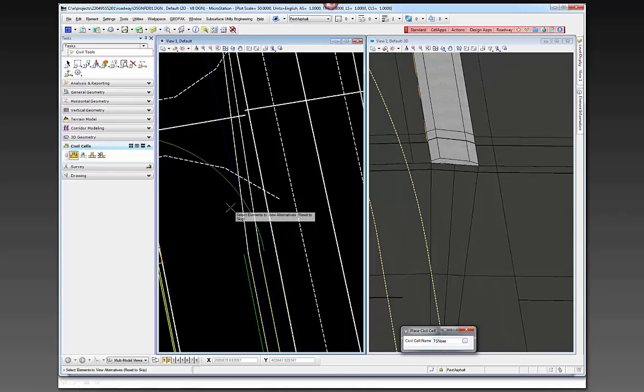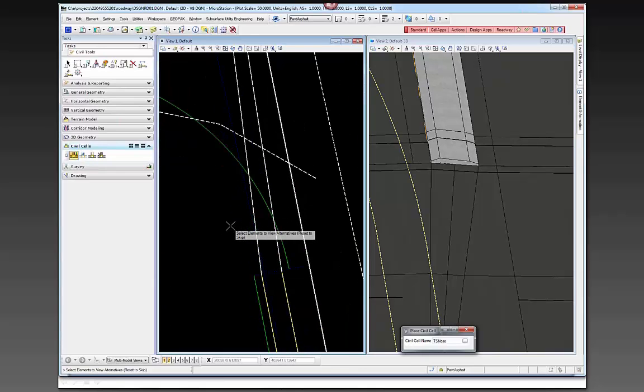And then it usually comes in at the orientation is wrong, so what you've got to do is just flip this, and then you flip this one as well, and then it will pop it in there, and it looks, from the plan view, it looks correct. And then you reset to change any alternates and accept the civil cell.